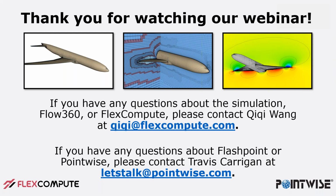Do we still need a watertight surface mesh or a watertight geometry for the mesher? Another good question. The prerequisite is what we consider a watertight and quilted geometry, much like we prepared in this case. That's the prerequisite to get the best results out of Flashpoint surface meshing. You can still give it anything and get a mesh, but you may need to do some cleanup of the mesh afterward using, for example, the grid merge tool.